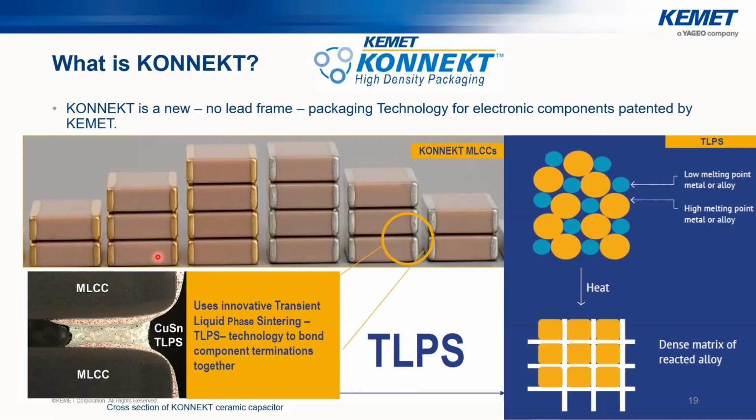And this kind of technique is basically using two types of particles inside, copper and lead. So the lead has a lower melting temperature than the copper, and when we heat all this together, the lead will melt on the copper alloy and form a very rigid and robust matrix, which will allow the connection with several capacitors in parallel.